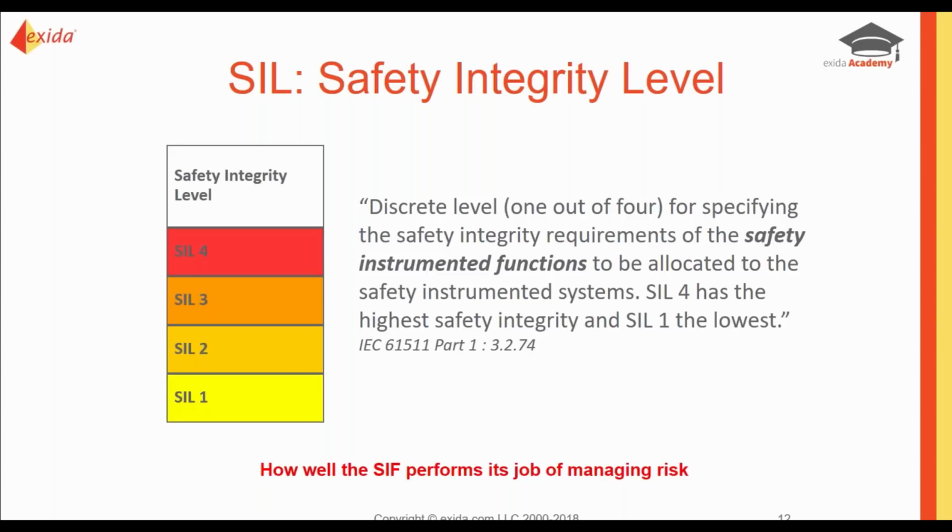SIL 4. One thing to note in IEC 61511, it really only defines SIL 1 through SIL 3 for the process sector, except for nuclear. If you find yourself in a SIL 4 situation, refer back to those details in IEC 61508. Once again, being that umbrella standard.